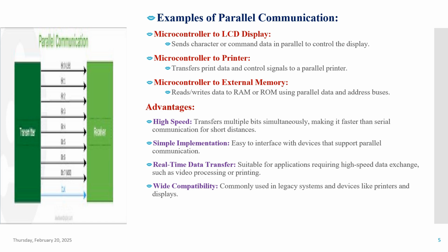Now the advantages of parallel communication. There are various advantages. High speed, that is, it transfers multiple bits simultaneously, making it faster than serial communication. Second one is simple implementation, that is, it is easy to interface with devices that support parallel communication, requiring straightforward wiring and control logic. Third one is real-time data transfer. It is suitable for applications requiring high-speed data exchange such as video processing or printing, where delays can be detrimental.